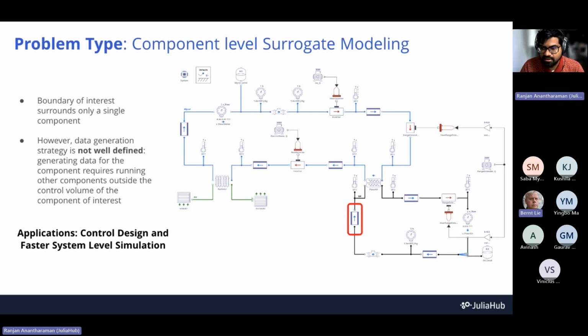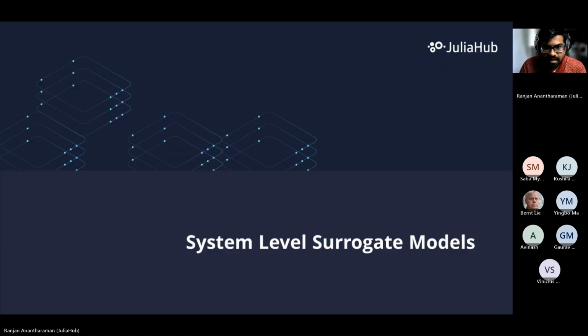And the other question is, even if you're validating this type of component in open loop, how exactly do you choose the input signals to perturb the system, given, of course, the system is non-linear. If the system were linear, you could consider a certain set of frequencies and so on. But since it's non-linear, how exactly do you do that? These are all open questions, but these are things that we're working on in-house. But these are the two axes that I want you to think about, the different stages of surrogate modeling and the problem types, to give you a sense of the richness of the problem.